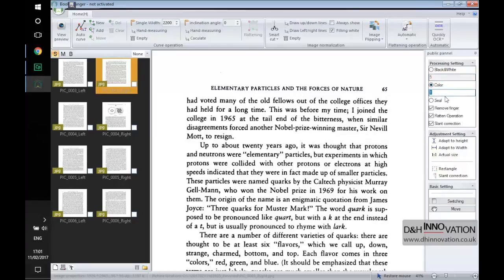In color mode, you can adjust the noise cancellation level in the scale from 1 to 6. The noise cancellation function will reach its strongest when the value is set at 6, and reduced to the lowest when the value is set at 1. When the cancellation function is at its highest level, it is possible that some details of the scanned image will be removed and cause blur on the image. We would recommend this value to be set at 3 to start.